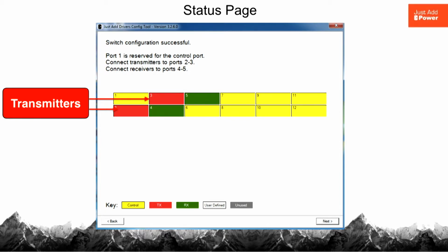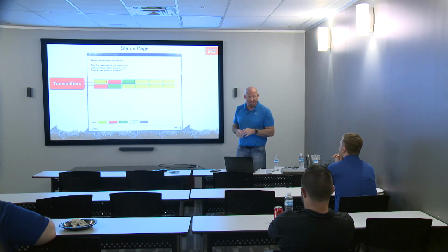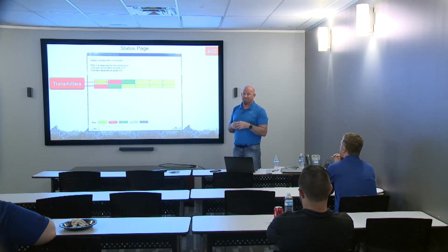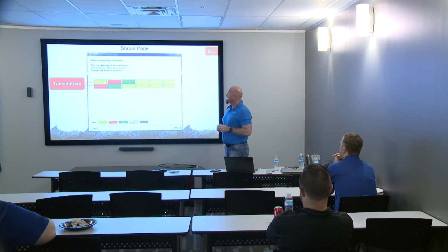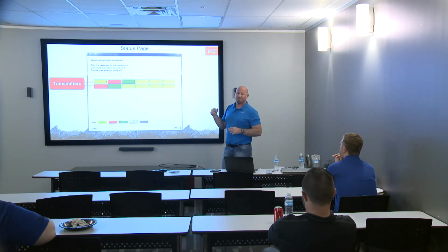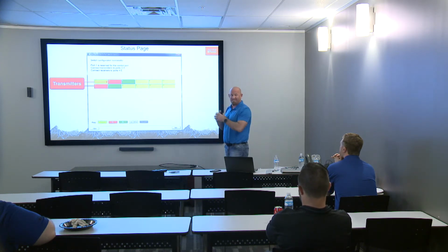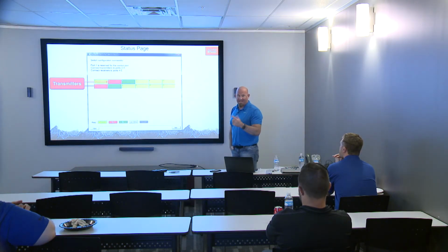One thing I'm going to talk about is, here you can see we have extra ports, and customers never change their minds, I always recommend adding an extra transmitter or two into the system. This way, it alleviates any problems of coming back 6 months down the line when a customer wants to add some sources. You would have to unplug those receivers and move them down the row. It's not really much of a problem on a little 2x2 system, but if you're working with like 7 transmitters and maybe 13 or 14 receivers, that can become a problem. If you get them out of line and you programmed your control system, you can mess up your programming. So I always say to add an extra transmitter or two here.